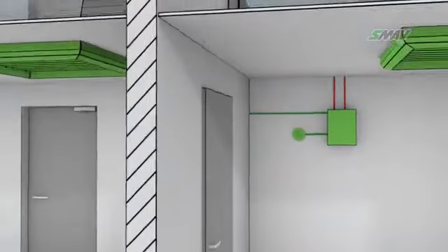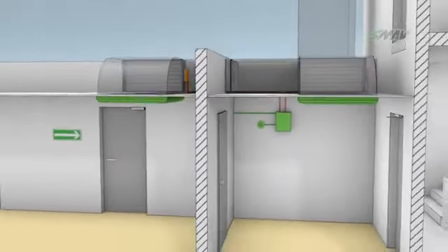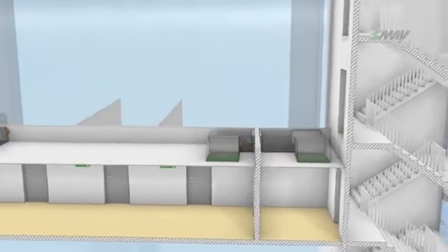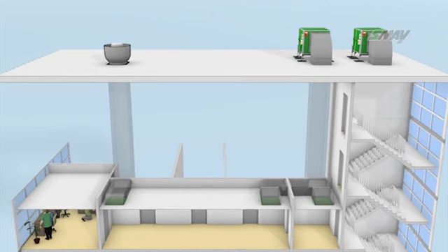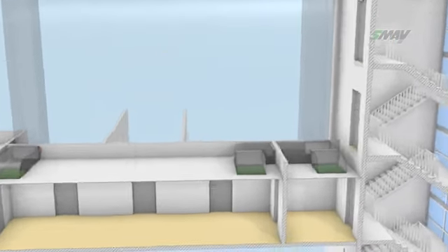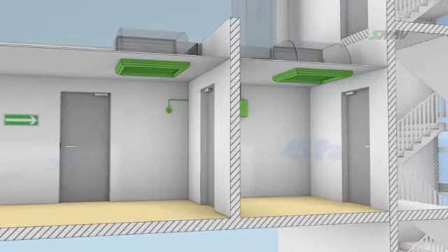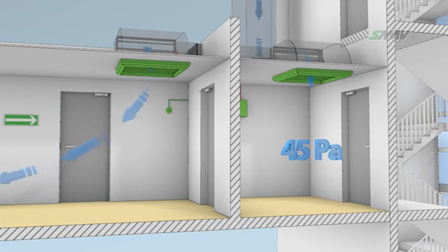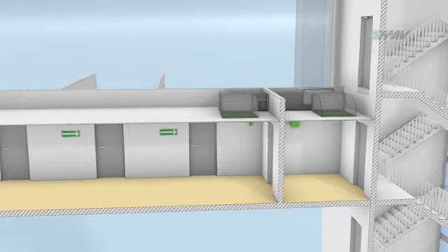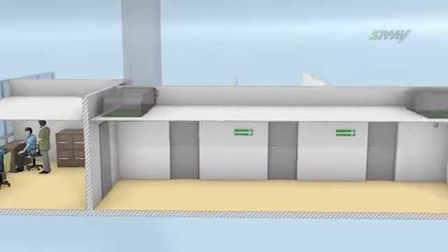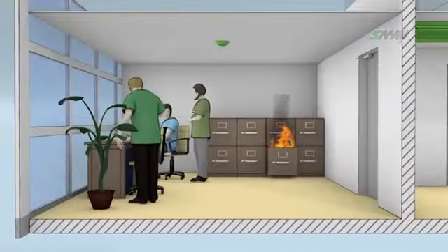The proposed system is an answer to the smoke extraction air compensation problems for corridors operated by constant capacity smoke extraction fans. The idea behind this solution, in the event of all the doors along the escape route being shut, is the simultaneous supply of a small quantity of air to the lobby, producing an overpressure at a level of 45 Pascal, and the supply of compensation air to the corridor, protecting against excessive pressure reduction within that space due to the operation of the smoke extraction fan.